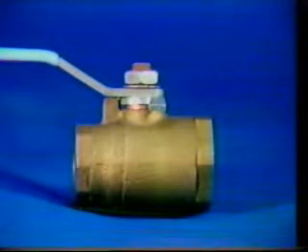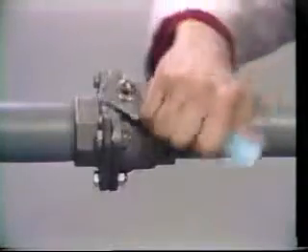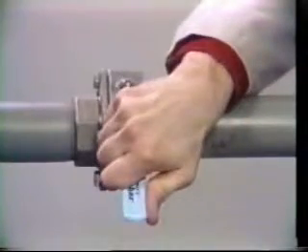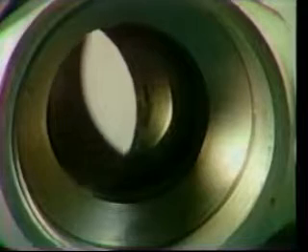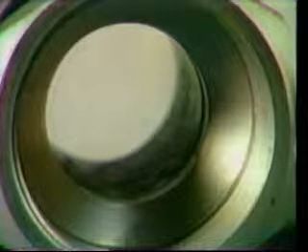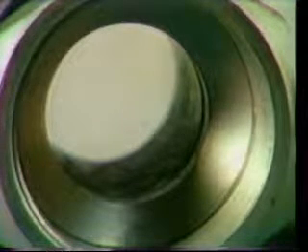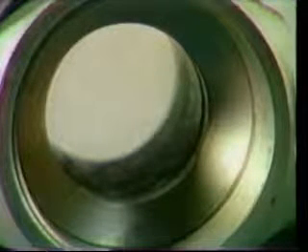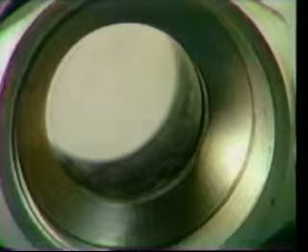Plug and ball valves are basically of similar design. Whether the sealing component is a plug or ball type mechanism, it will operate in an open or closed position with a quarter of a turn. Maintenance and repair are facilitated by the relatively simple assembly. These types of valves are not recommended for throttling because partial opening would expose the ball and seat to high velocity flow. It should be noted that even when fully opened, this type of valve may snap shut under high velocity flow conditions, creating dangerous and undesirable situations.